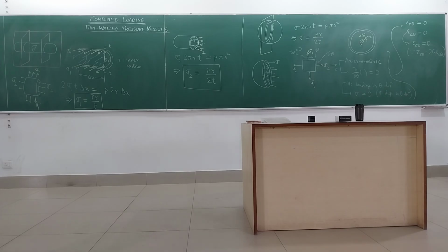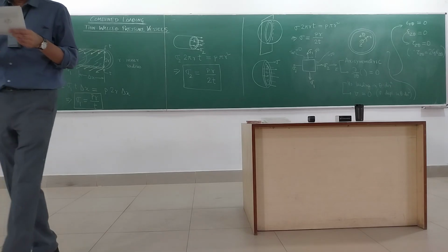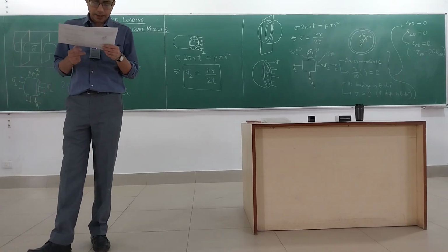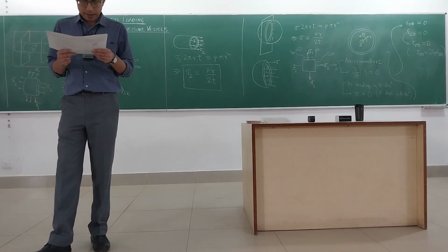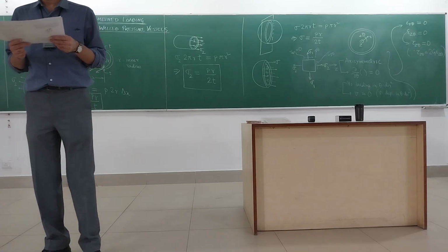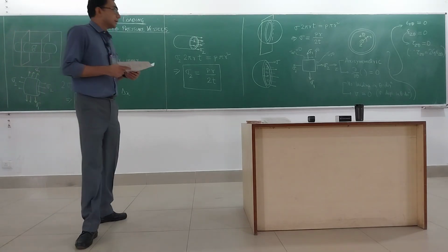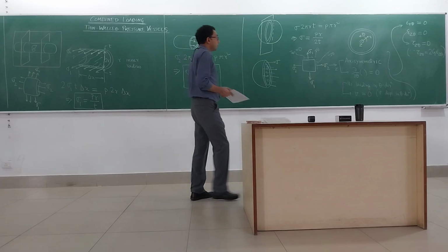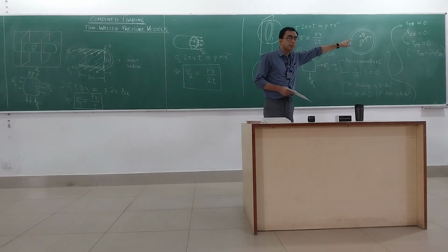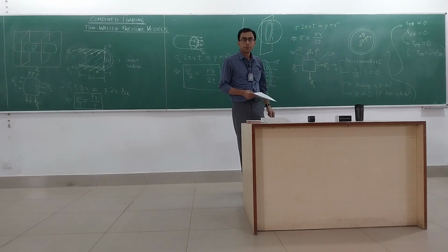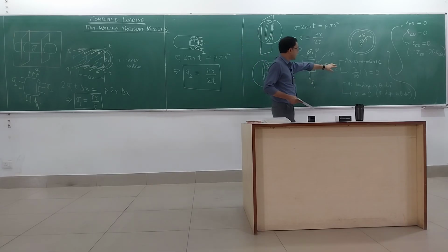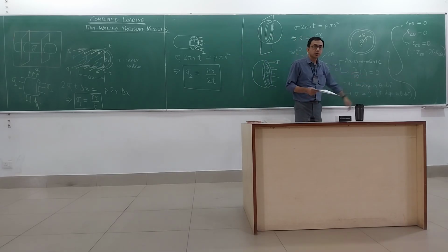Here the epsilon r theta is a half, within bracket 1 by r del u del theta plus del v del r minus v by r. Just check whether what I said regarding epsilon r theta being equal to 0 holds true. From axisymmetry, del del theta of anything is equal to 0.